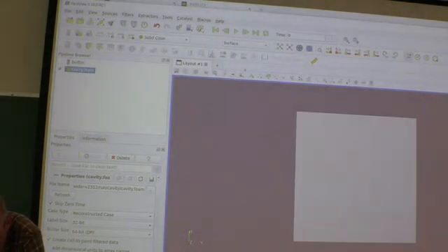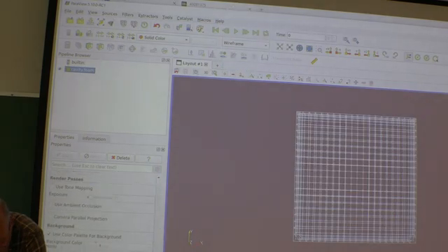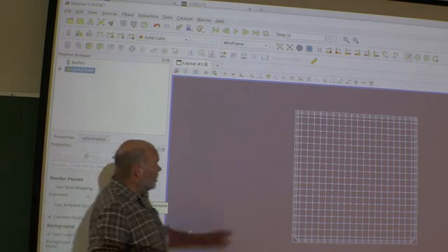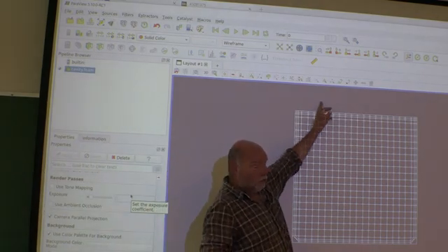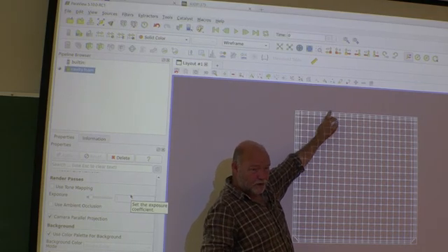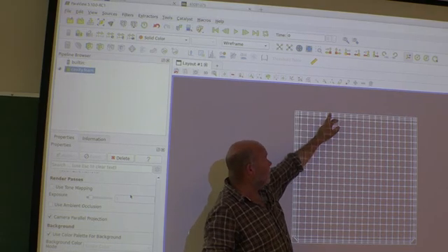So we just apply wireframe and parallel projection. So now we have also stretched towards the top wall. And for this case, this is actually quite crucial. Here is where all the physics happens anyway. So it's quite important to resolve this boundary layer well.